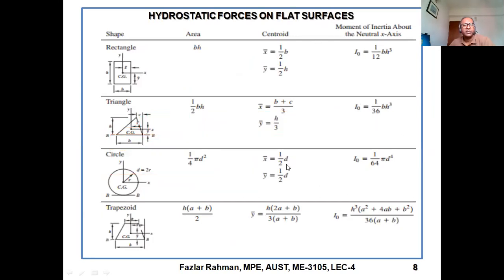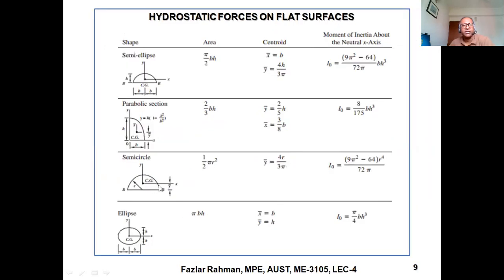So in that formula sheet, what is our area? Semicircle, right over here. We need to use this one. So you see location of CG from the plot is given. Y bar is this. I naught, you can use this formula. Area half pi r square. So you need to be careful. In our case, ours is upside down. That means the flat surface remains at the top. So if right over here is CG, we need to have this distance. We need to calculate from here to here, and this distance will be this value. So you see they are giving it from the flat edge, not from the bottom. Okay.